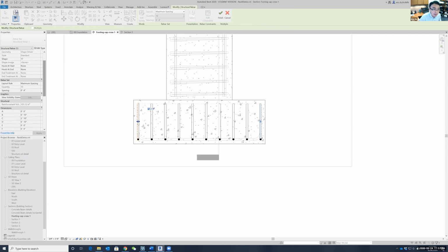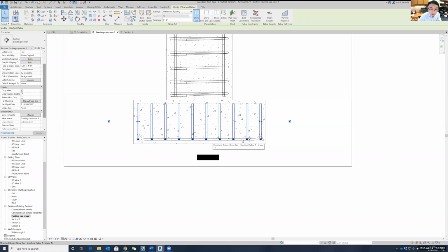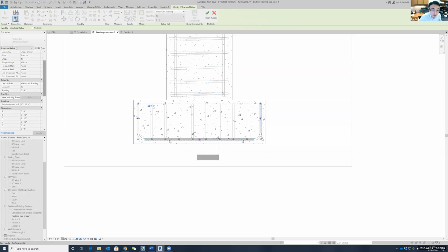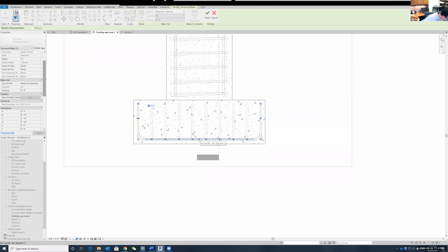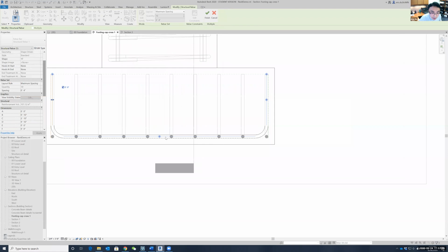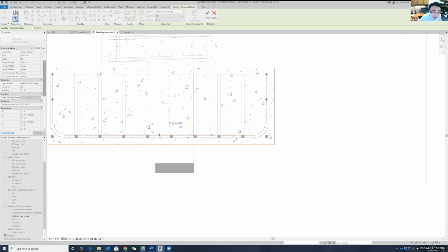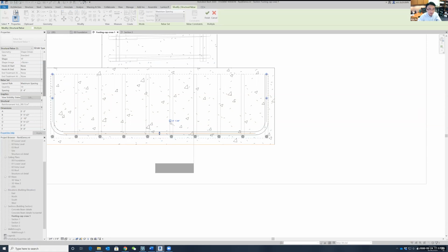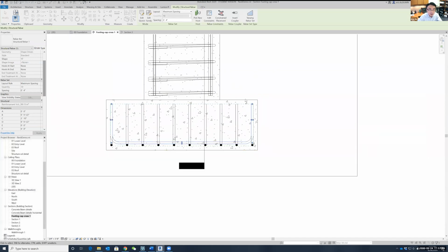All right. Select this rebar, edit constraints. And we need to change the number. Where's the number? Here it is. Okay, so once I select this rebar, you can basically change the number here. That's actually the quantitative way to adjust the location. So let me just change this one to negative 1.75 inch. Now it moves up.